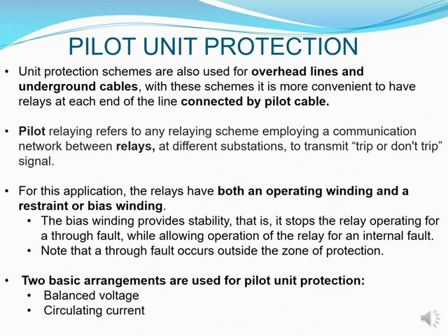So in this lesson, we're really going to be looking at our unit protection on overhead lines as well as underground cables. And for this purpose, we then have these schemes, which we say can be more convenient if we have the relays at each end of that line or cable connected by this pilot wire or pilot cable that we're talking about.